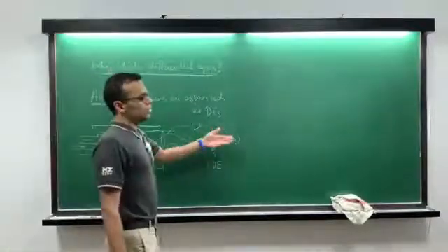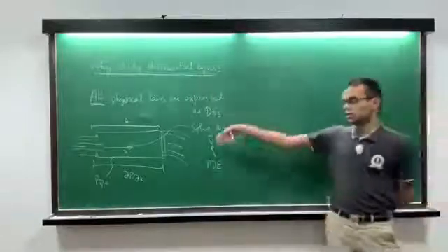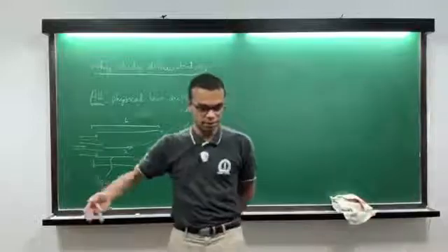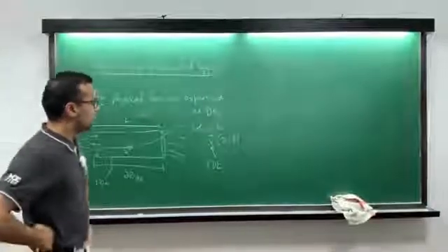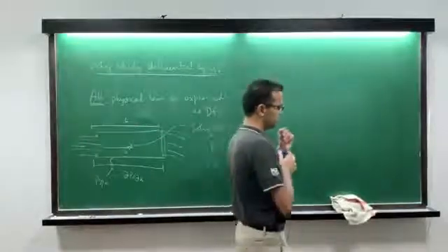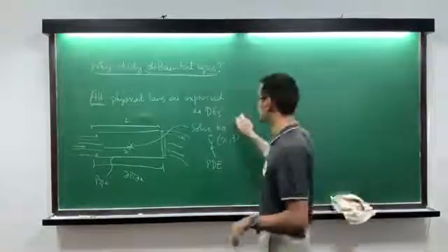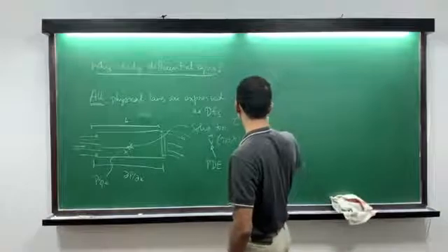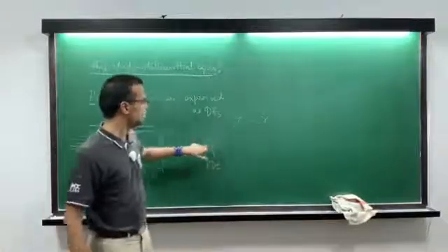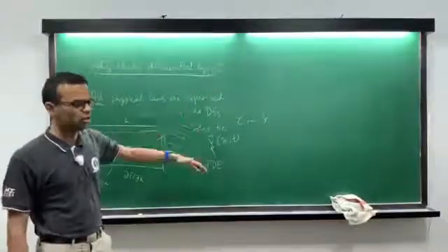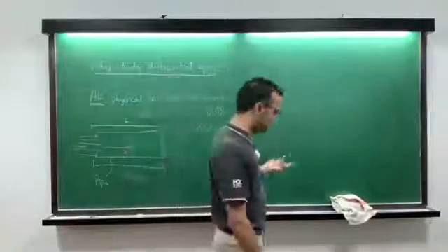It's a result from a physical law. What is the physical law? Well, the physical law is that momentum is conserved. So you take any cross section, you write down the equation of momentum conservation, which is written like a differential equation, and you have to put in something called a constitutive law, which for water at least is Newtonian. You can write that the shear stress is proportional to the strain rate. That's a constitutive equation, and you can write the strain rate in terms of the velocity, and then you put all that together, and long and short, you will get a differential equation that governs this, a partial differential equation. Again, you have a differential equation.